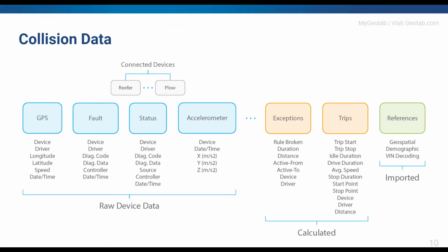Then status information could be also very interesting. So on the status information side, you can see what was the cranking voltage during that event, right? Was there some anomaly during the collision? What was the RPM, the revolutions per minute showing? So typically you're driving, let's say you're on a highway, and then you have suddenly a crash. You will notice that the RPM might be still ongoing after the crash, but then it suddenly just stops.